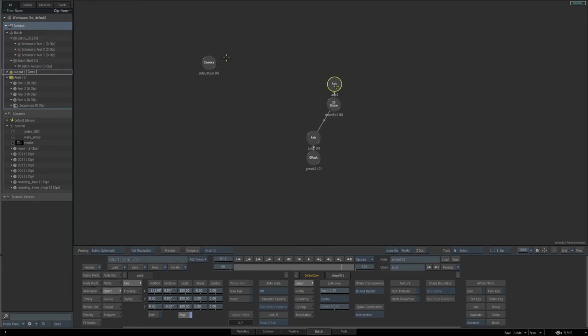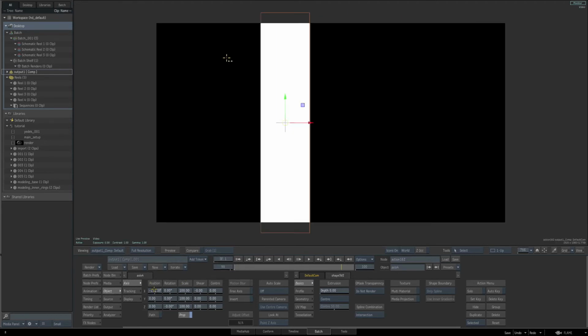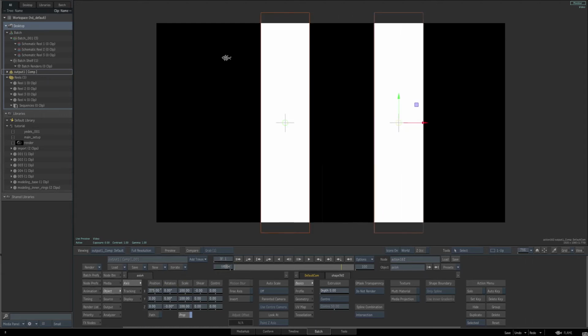Let's go back to the action schematic, where our mask and our 3D geometry is, and we want to duplicate this. So select the top axis with the Alt key or Option, which selects all our nodes, hit Control D to duplicate everything. Now go into the result view with the top axis of our duplication selected, and then shift it over to the right with the X parameter.